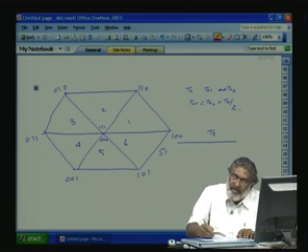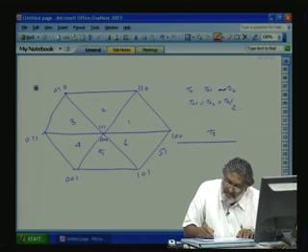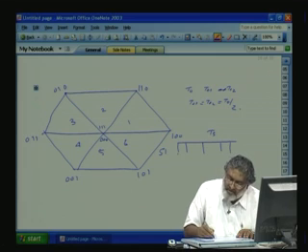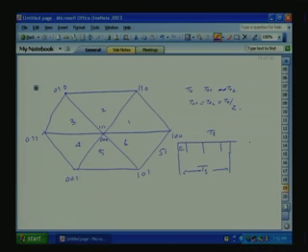Let us take the T01 period, then T1, T2, and next the T0 period. This is our Ts. T01 and T02 are the same. In sector 1, we will start from 0 0 0, then 1 0 0, then 1 1 0, then 1 1 1.